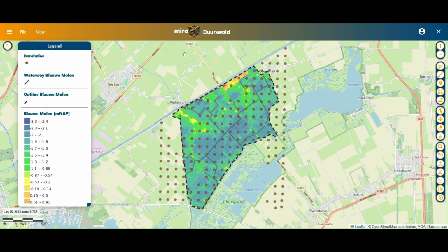In this session, we will explore the subsidence tool. This tool allows users to simulate ground sinking due to compaction, settlement, and oxidation in peatland areas under different surface water scenarios. It can also be used to report the CO2 emissions avoided as a result of these processes. Let's take a closer look.